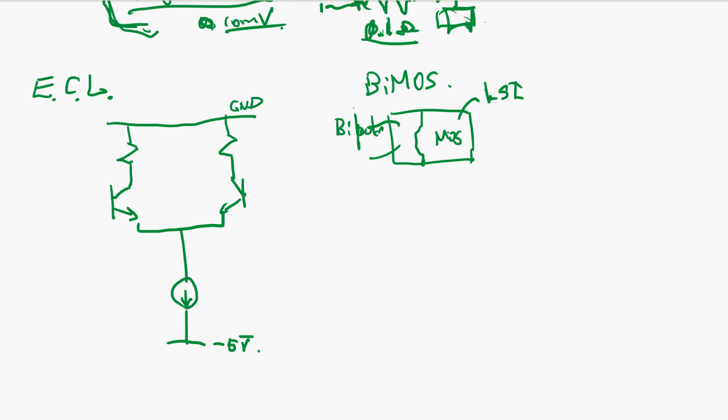Now on the single chip, this will be like plus 5 to ground, and digital is plus 5 to ground. But you cannot connect this on the chip because the logic circuit side, many switches turn on and off, and it's quite noisy. This has a lot of noise, and if you connect them together on the chip,